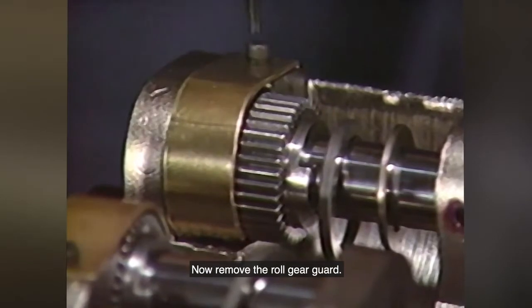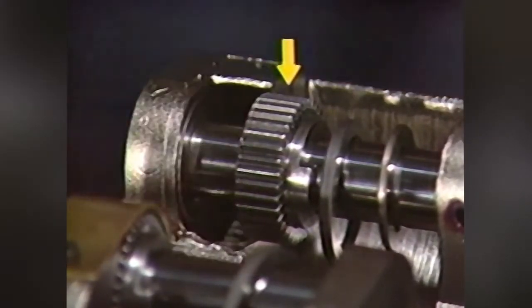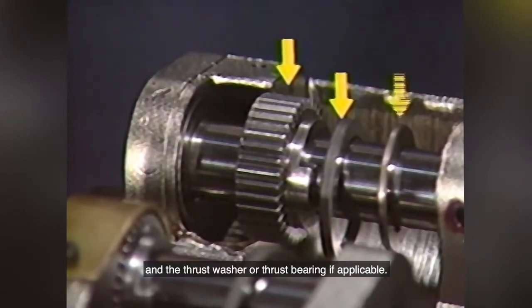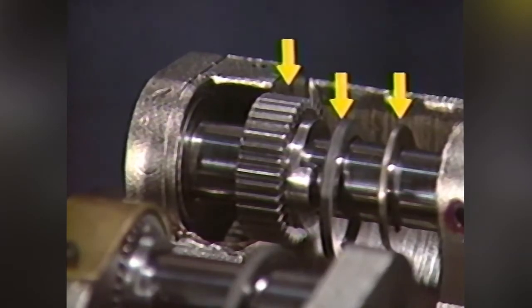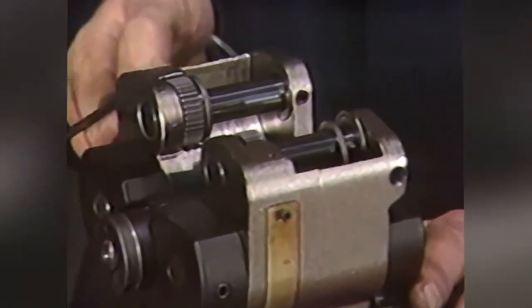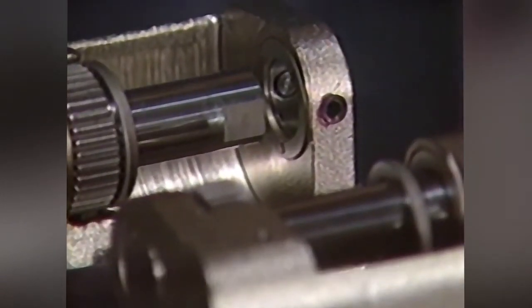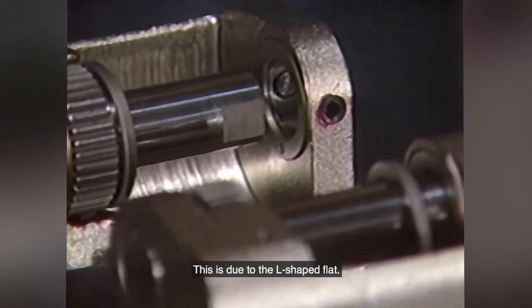Now remove the roll gear guard. Observe the positions of the roll gear washer, and the thrust washer or thrust bearing if applicable. Loosen the locking set screw and remove the roll pin. Notice that the roll pin can only be removed in one direction. This is due to the L-shaped flat.